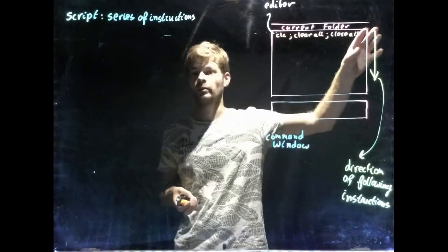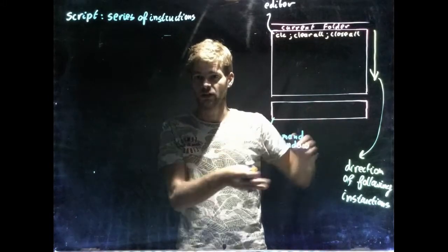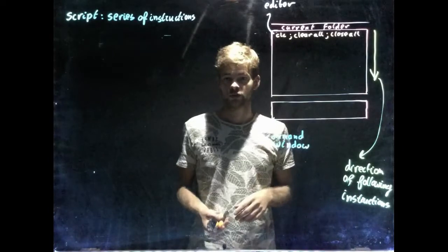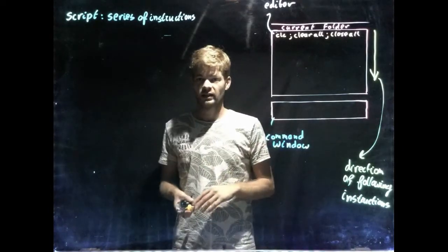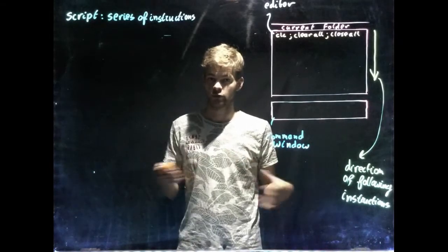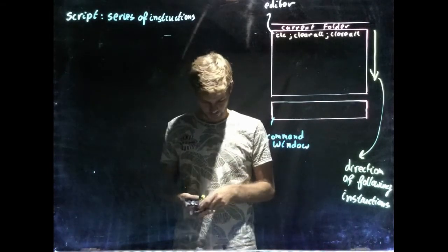So if you've got some variables stored in a previous run, MATLAB will reuse them and not erase them. So it's always good to state this before you start, so everything is clean and mistakes are not made because you saved variables you're not going to use. That's always very useful to do.